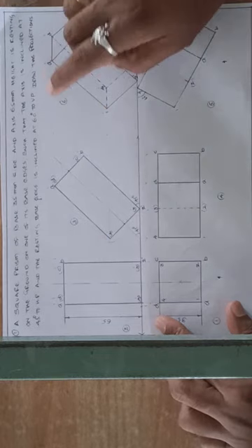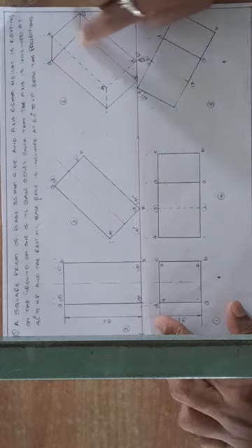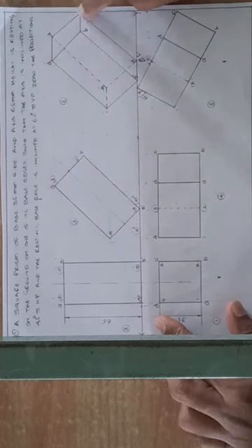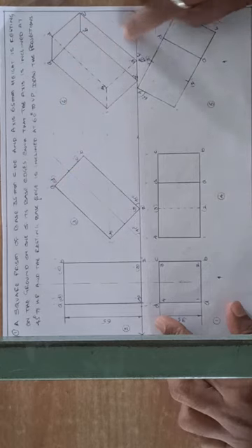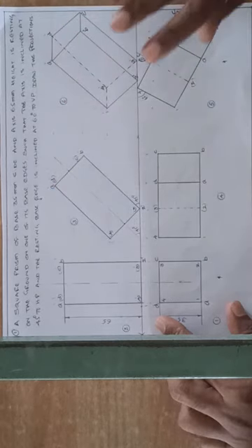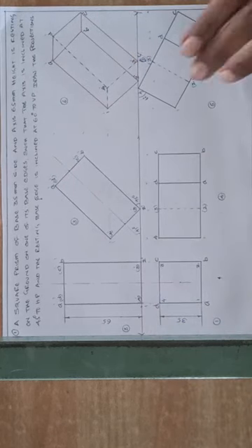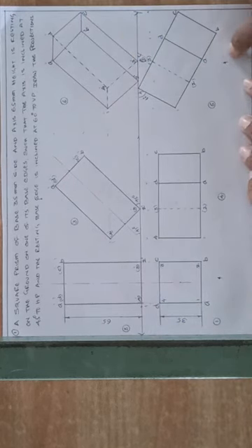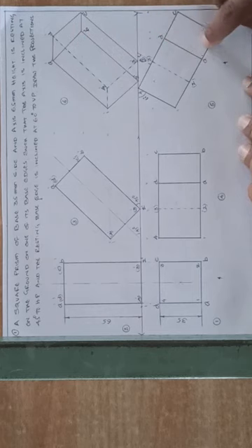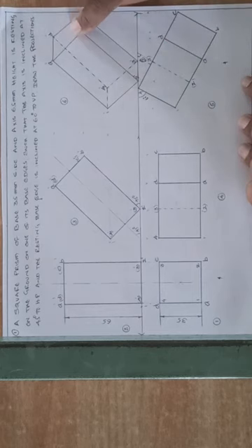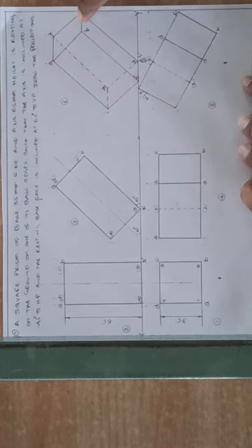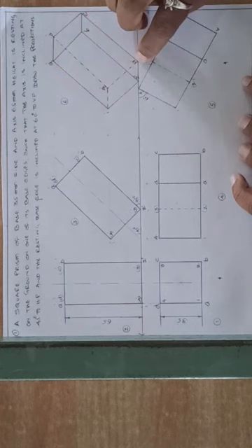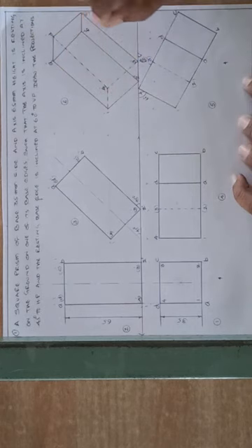Similarly, A vertical, A horizontal, A dash. B vertical, B horizontal, B dash. C vertical, C horizontal, C dash. D vertical, D horizontal, D dash. So like this. Okay. Now when you are joining the faces, looking from here, you can see this complete face. Make this face full dark, fully visible. Then join A dash, 1 dash, B dash, 2 dash, C dash, 3 dash, and D dash and 4 dash in bracket, right.